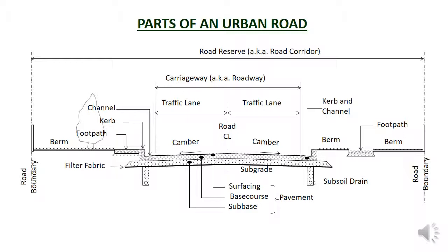The part of the road where the traffic flows is the carriageway, which is also known as the roadway. The surface of the carriageway usually has a watertight layer known as the surfacing. Surfacing may also be called a wearing course or top course. The surfacing provides a safe surface for vehicles to move on and holds the surface together under loads from the traffic, as well as preventing water entering the underlying layers. The most common types of surfacing in New Zealand are chip seal and asphaltic concrete.